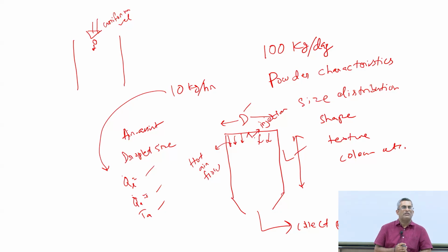Okay, so for that purpose, you will write the transport equations for the particle. For the carrier phase, in the case of the airflow, you don't have to, because the airflow velocity is uniform and one particle is not going to modify your airflow temperature, velocity, etc. Then from that you can estimate the distance that I will need till the time the water evaporates.